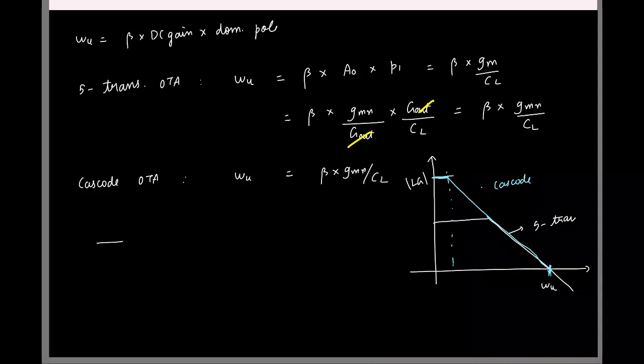So basically you have a GM like this. It will have its own output conductance, and say you have a capacitance at the output. So what is the best case value for G out? What is the ideal value for G out you want? R out is infinite. What is G out? Zero. Okay. So if that happens, what will happen to the dominant pole?